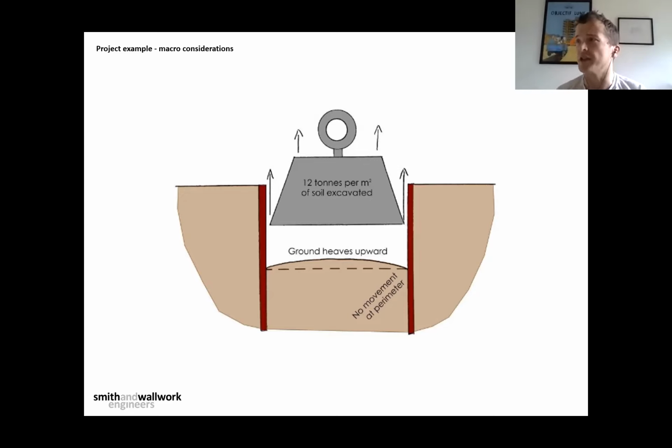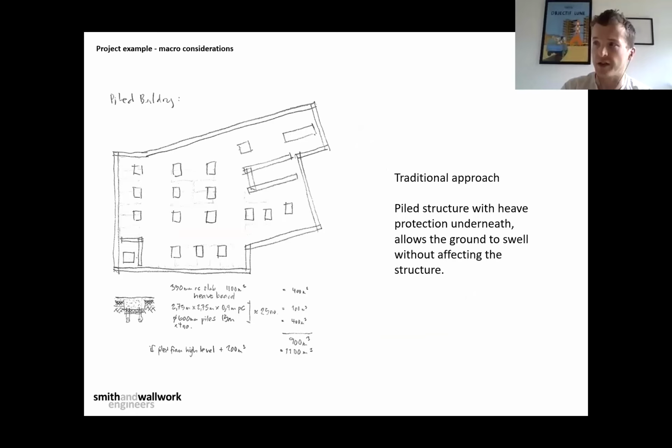And from the original ground investigation, the comment in that was that the ground heave of an excavation this deep and of this sort of footprint could be as much as 100 mil. And so typically, historically, I'm sure many people will have come across that the way of dealing with ground heave in a basement is you suspend the basement slab.